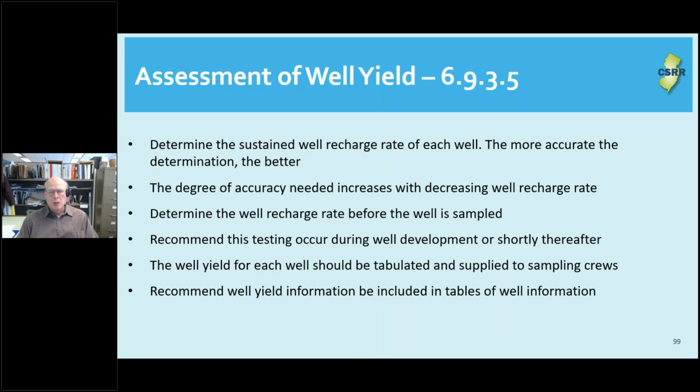The determination of a well recharge rate should occur before the well is sampled so that this information is available to the sampling crew. For existing wells where this information has not been determined, it is recommended that actions be taken to determine the recharge rate of the wells.